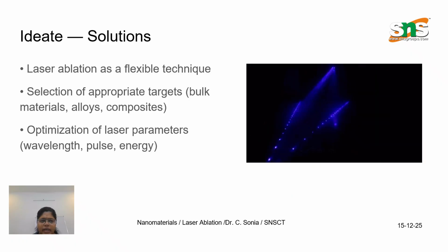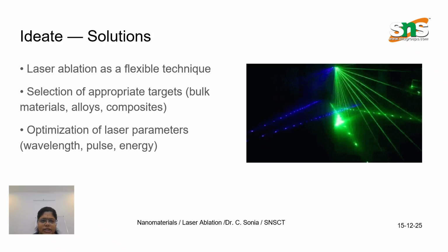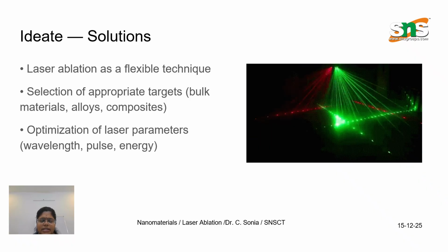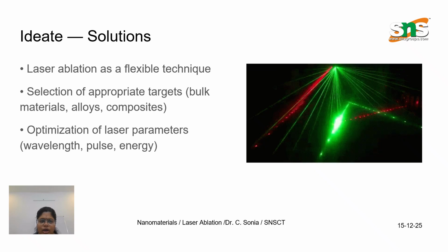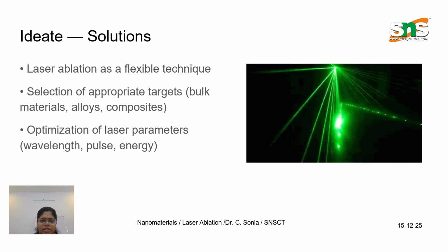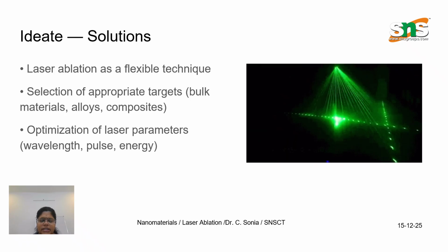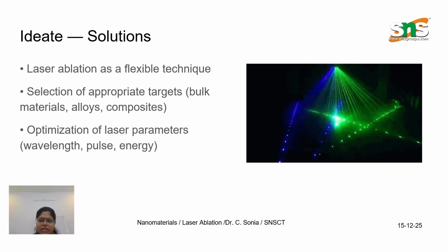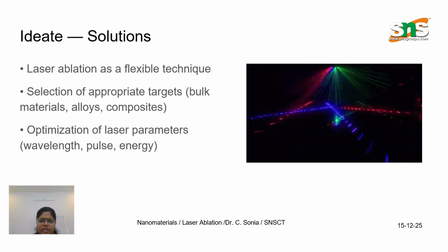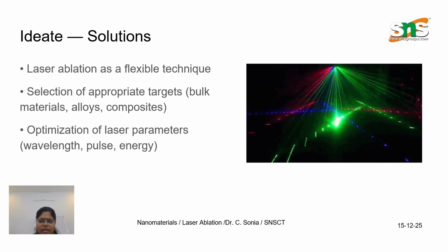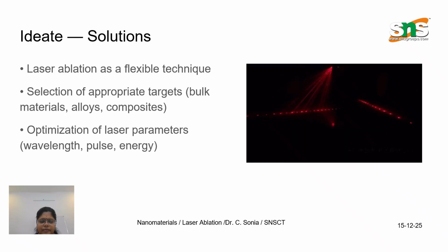So the idea behind this is that laser ablation is a flexible technique. Selection of appropriate targets like bulk materials. The bulk materials may be an alloy or a composite material. Then the optimization of the laser parameters. That is, we have to optimize the exact wavelength. The pulse of the laser has to be set right, and the energy of the laser beam should also be adjusted.